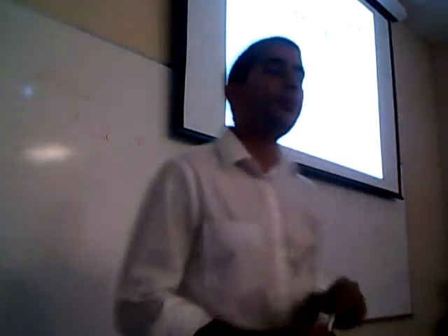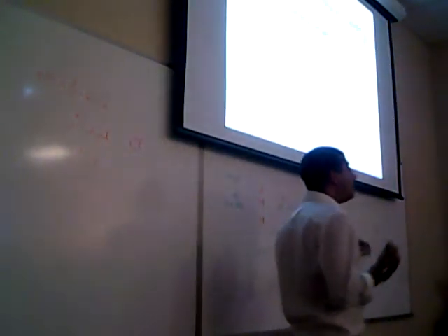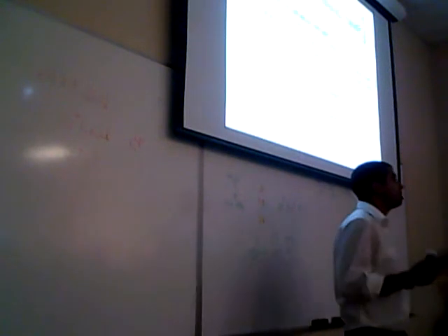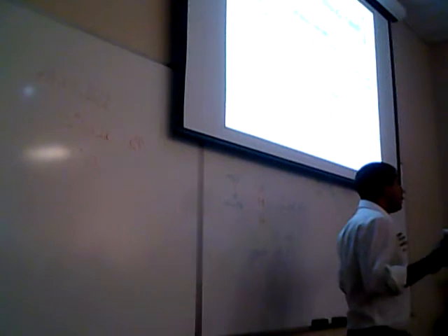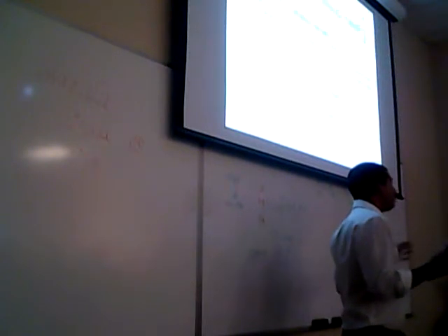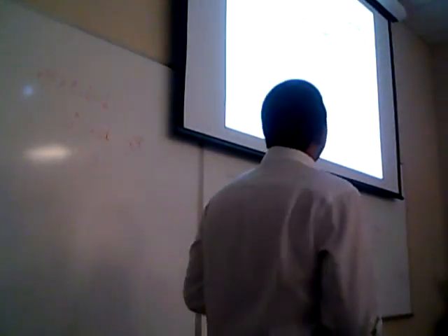That is the reason that sometimes we call it live steam. Live steam is the real steam. Sometimes we have 40% of live steam inside a volume of steam. That means that we're going to have 40% of water inside the steam. That is the reason that we call it steam quality.